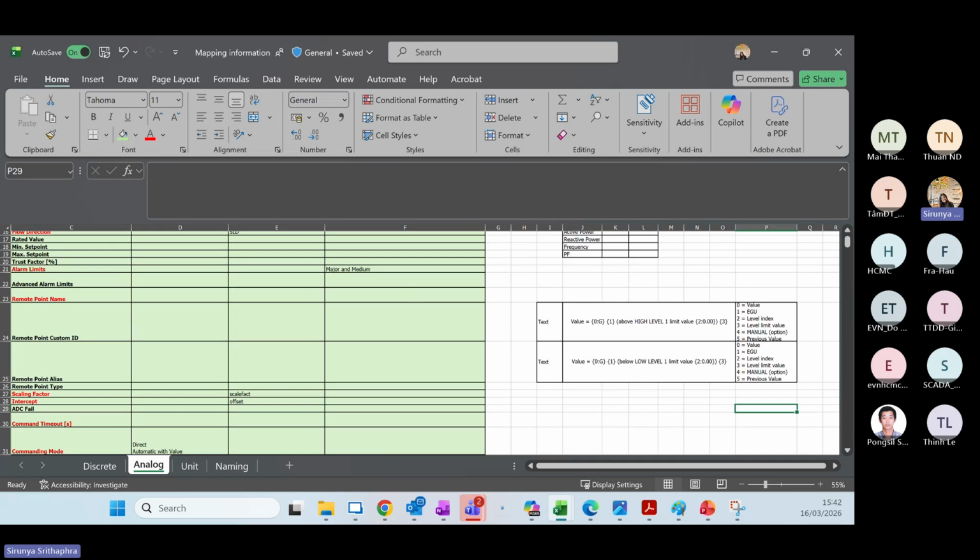If we don't, we will create a simple ICCP communication and send some signal to your system, just to check the connection and display the value or control only. And that means we will go with IEC 104 for all if you don't have ICCP, right? Yes.